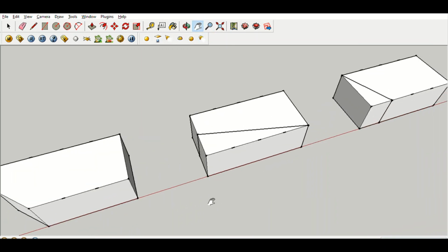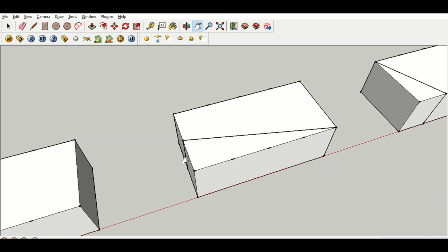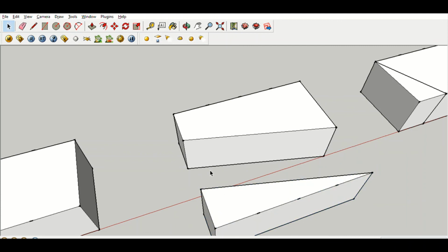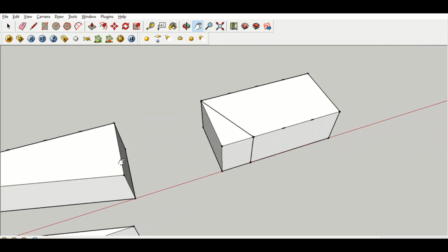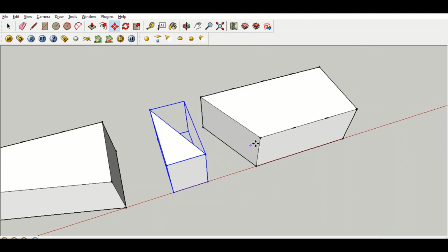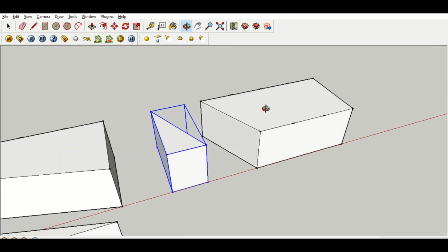Now if you cut the brick half from this and you match the corner like this, you will get the brick like this. This will be called beveled closer. Now if you meet the corner and the first fourth part of this, you will get a brick like this. This will be called mitred closer.